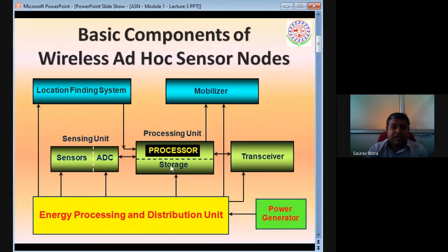Apart from the processor, there are sensors. What all do you want to sense by using that sensor node? Not necessarily one sensor on one board. Generally, it is a multi-sensor board. In an industrial area, we can sense, suppose, temperature, pressure, three or four different kinds of gases and their concentration in the air, methane, heat, airflow, some 7, 8, 10 different sensing parameters that we can sense by one sensor board. That is called a multi-sensor board.